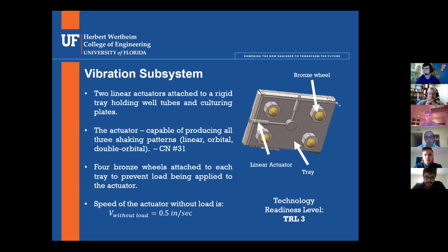The used actuators are 30 IPM SPAL linear actuators. These actuators will be supplied by a power source of 12 V DC. The speed of each one is half an inch per second with no applied load, and the static load of each one is 500 pounds with a stroke of 2 inches.